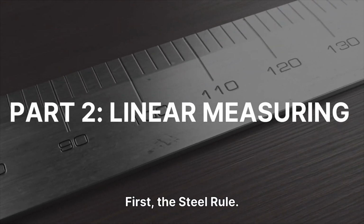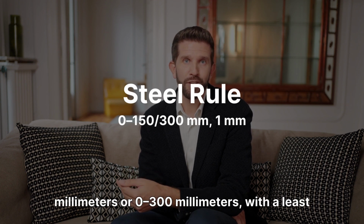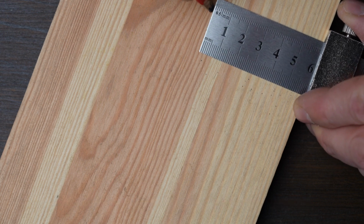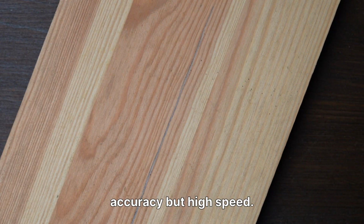First, the steel rule. It has a measurement range of 0 to 150 millimeters or 0 to 300 millimeters, with a least count of 1 millimeter. Steel rules are used for rough measurements, layout marking, and fabrication work, offering low accuracy but high speed.